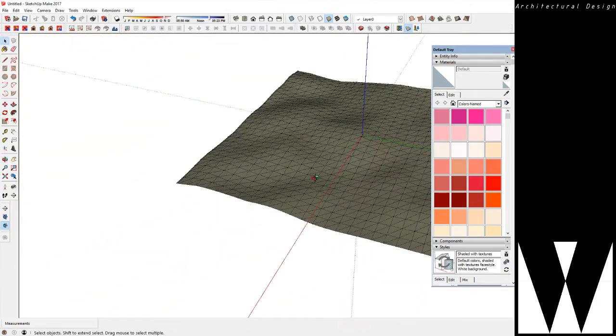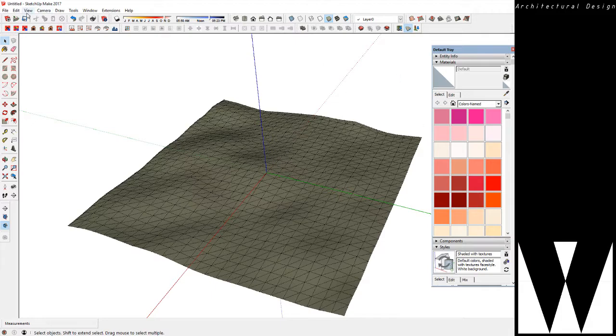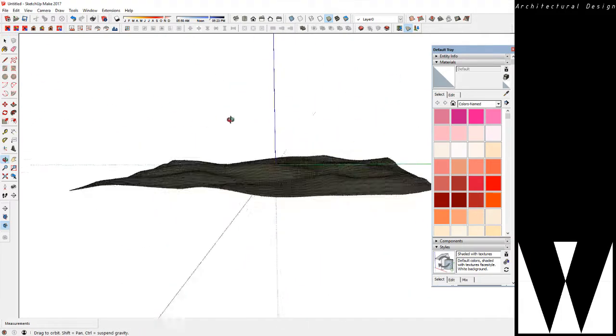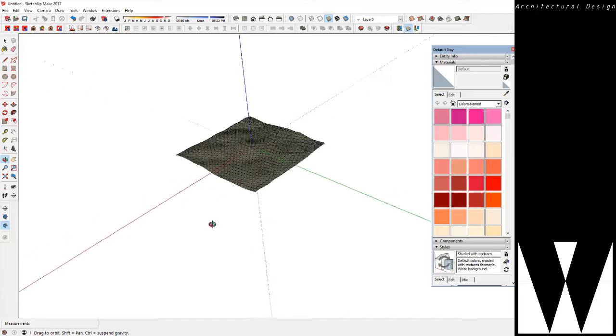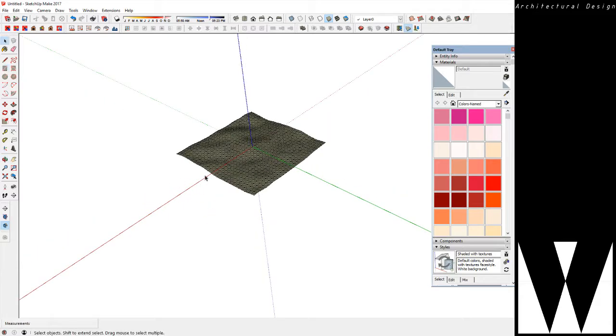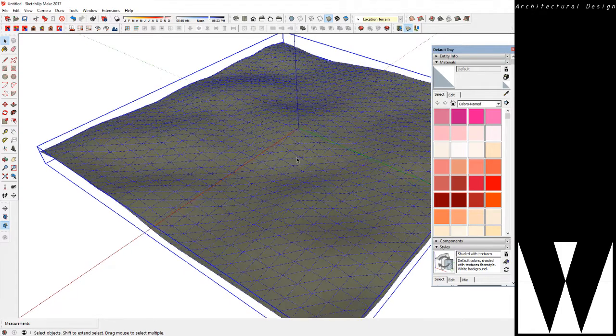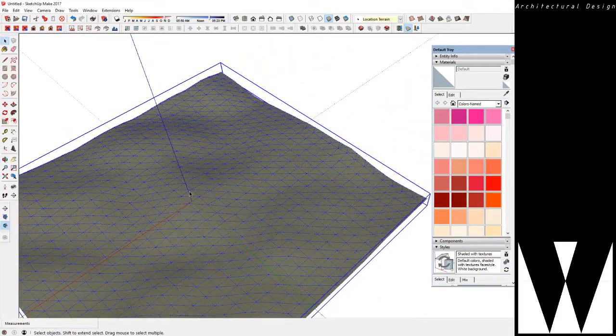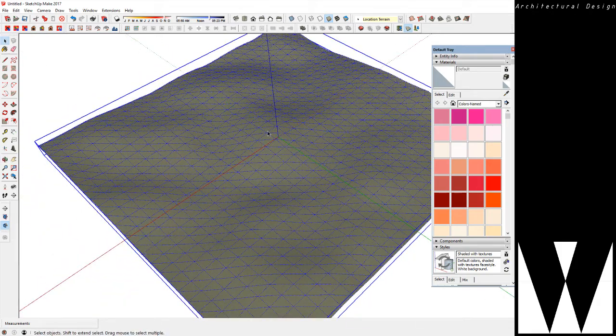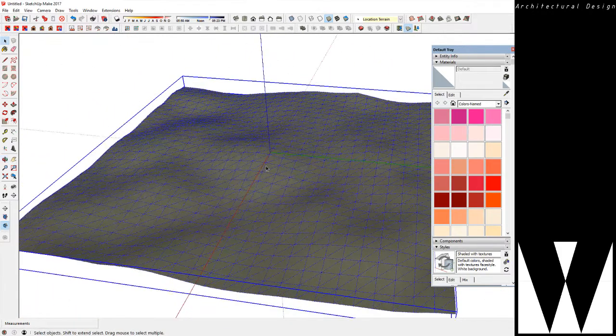But ignoring that for a second, I'll just show you what is possible, or how you work out the contours. Just to define contours, a contour is a line that joins all the same elevations in a particular drawing. So in this, a contour should be drawn around the top because that's approximately all the same elevation. It could possibly arc around these things, so it kind of goes around in circles, connecting all the places with the same height.